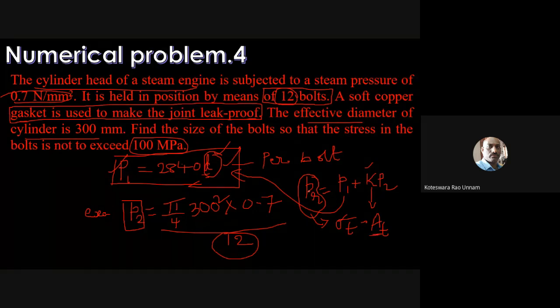So now if I take this equation, AT is unknown and even P1 is also unknown, but that is in terms of unknown D value. So that means two unknowns, one equation, you cannot solve for this. So then what I'll do is, I'll try to find out this AT value in terms of this D. Like I already told, whenever data is not available for you, you can calculate this AT based on your DC, that is core diameter, π/4 DC square.